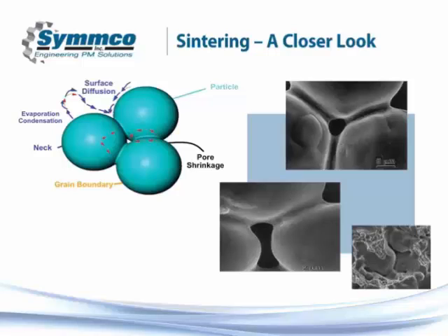Sintering takes the areas at which those particles were touching and bonds them. That heat is strictly energy. Energy moving around those contact points creates a bonding. And it's really key to take a look now over to the bottom right. What you have there is a scanning electron microscope view of a part that was fractured to confirm it is truly a bonding. That's integral to us providing a very good part to you, key to us providing the size specifications you need, and key to making sure that it's correctly sintered.